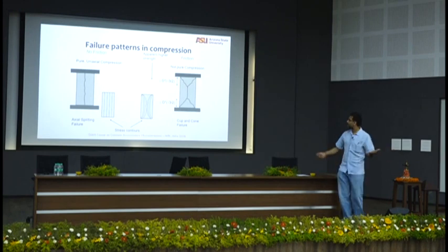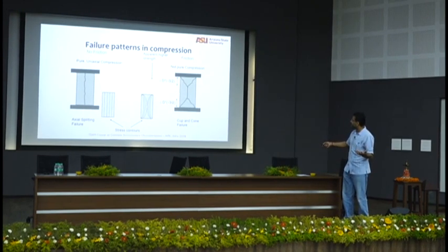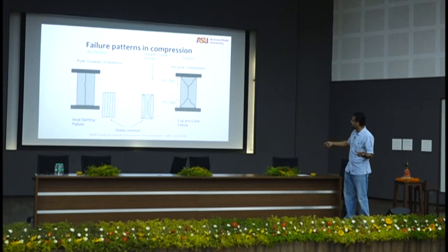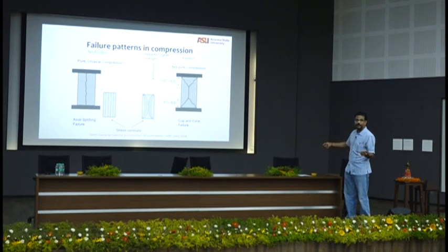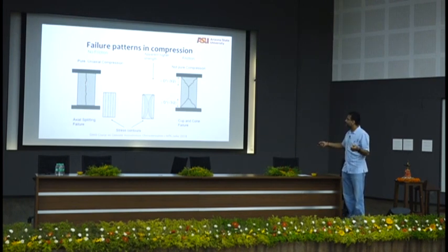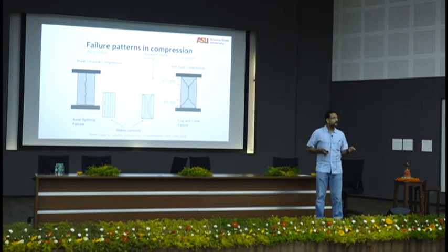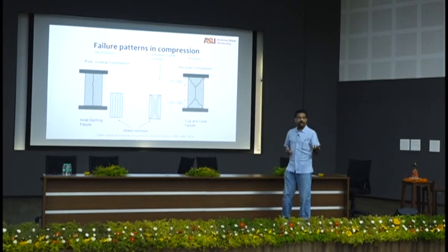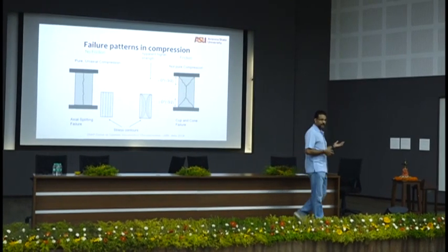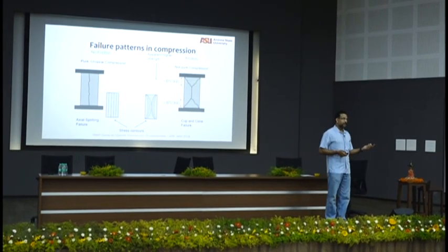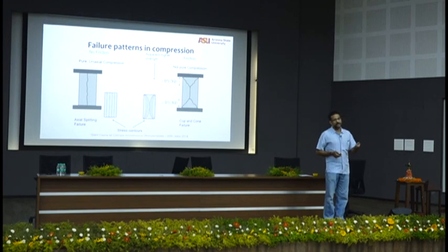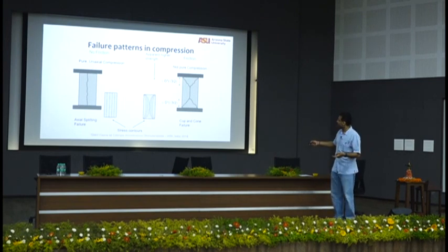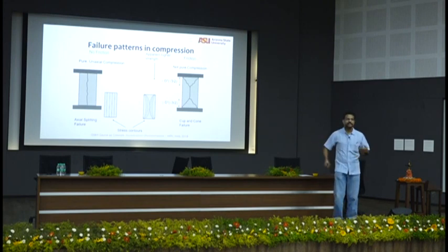You cannot. So you will never have the pure axial case, and if it's pure axial, the stress paths are going to be like this. But what we have, and also one more thing, you are compressing concrete not with concrete. You're compressing concrete with typically steel. Steel has 5 times more elastic modulus than concrete. For the same load, therefore, your concrete will deform more and your steel will deform less. Which means at the steel concrete interface there is relative movement.